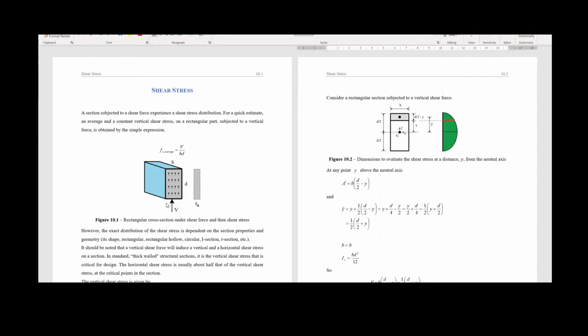If we have, for example, a shear force internally in a beam, doesn't matter if it's simply supported or cantilever, and the value of this shear force is V, if we divide this V by the area of the cross section, we're going to have a value in units of stress, the same as we did for axial stresses. So we are going to have a uniform distribution of the shear stresses. Yes, I can change that for you to see more clearly.